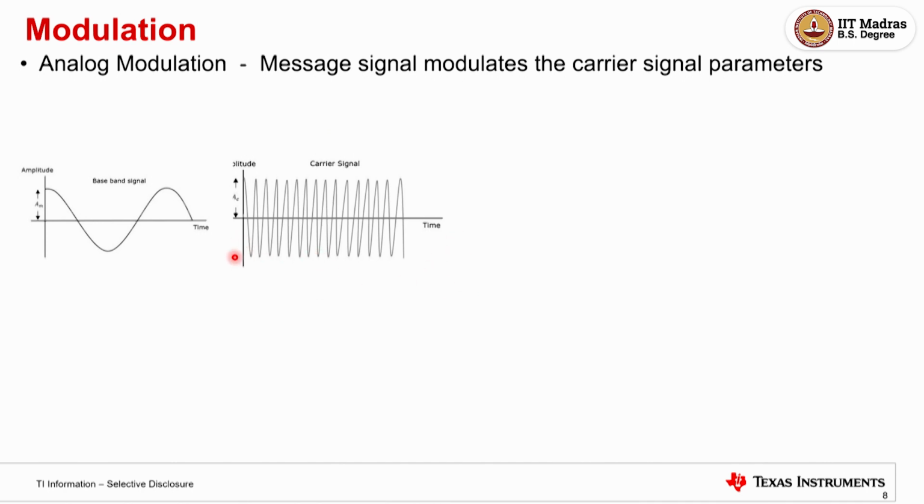When you say amplitude modulation, what I do, right? Let's say I multiply these two. Somehow I figure out a block that does multiplication of this and this. Basically, it just changes this guy's amplitude, meaning the carrier signal's amplitude or the level, based on this. So that's what this is.